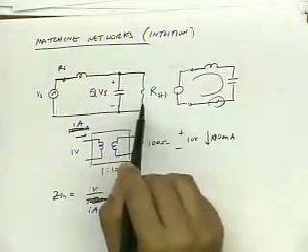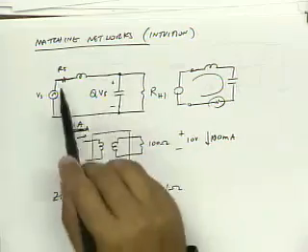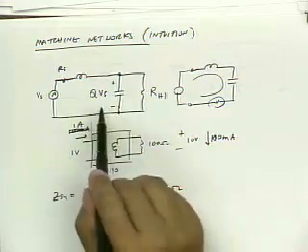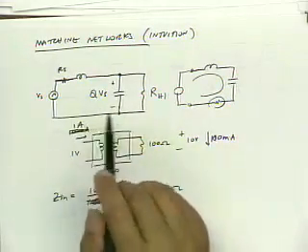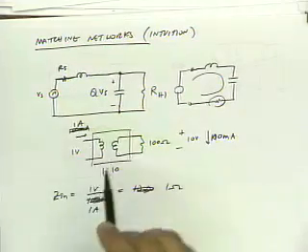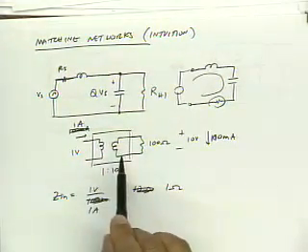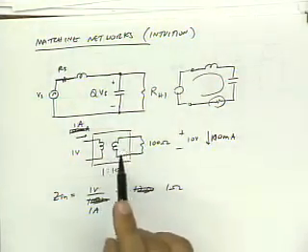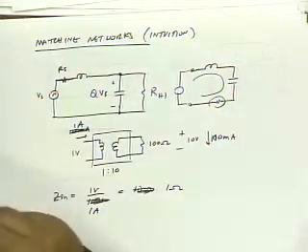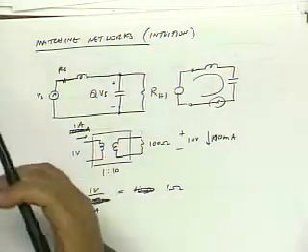But the important point is that the reason an L matching network works is because it can boost voltages and currents by a factor of Q, just like our transformer does. And intuitively, you would say, well, if it boosts it by Q, then it should go up like Q squared, right?